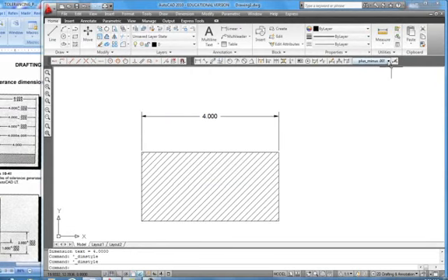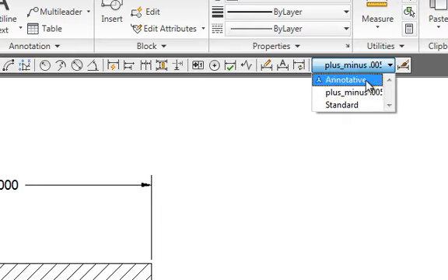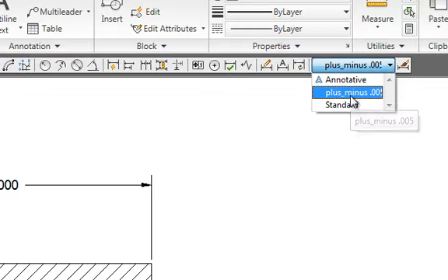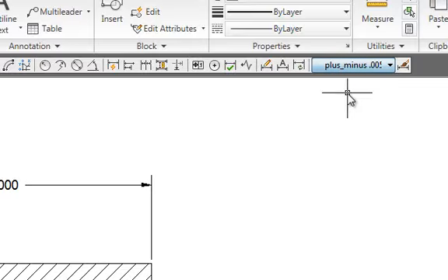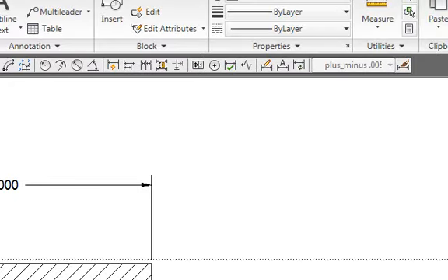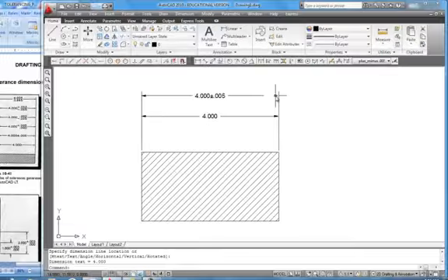Now you can see, this is why I wanted your dimension bar to show up, it's because you can see all of your dimension styles loaded right here in your dimension bar, and that's not something that you can just see right here in your regular ribbon. So if you don't have the dimension toolbar open, that's not readily accessible. Alright, so if we choose linear dimension now, we can click on that and just create that same dimension again.